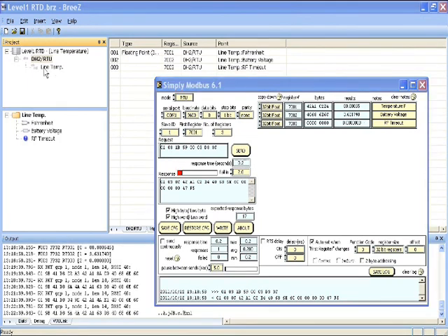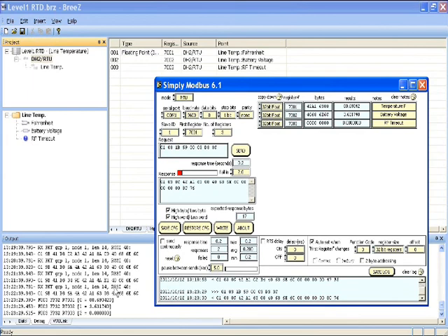We have now completed the Level 1 RTD line temperature Breeze configuration file build. We updated both pieces of hardware with said file, and then we confirmed that they were delivering data back through debug and that the Modbus request block was being responded to in a correct manner, that all data points were delivered accurately to the Modbus master. This can be easily accomplished with multiple end nodes.